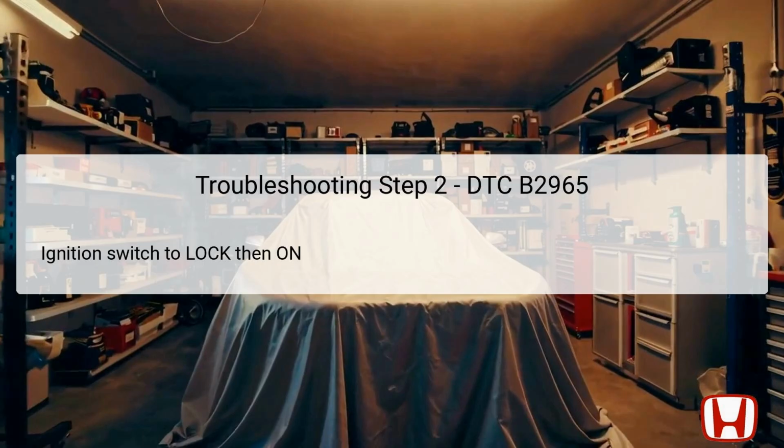By switching the ignition off and back on, it allows the onboard computers to perform a startup self-check and re-establish communication between components. This step often serves to reset any temporary faults and confirms whether the initial DTC was an isolated occurrence or if it persists. Ensuring the vehicle is in the proper state is essential before moving on to further diagnostics.